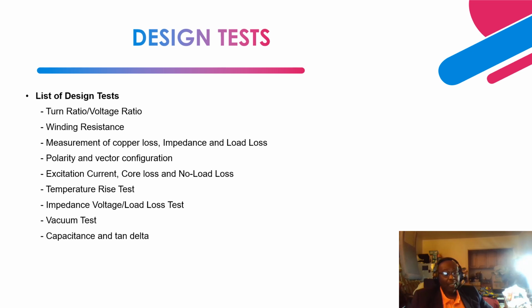And also, during filling of the transformer with oil before energization, that test is done under vacuum to make sure that there is no gassing or bubbles that are going to form. Because those gassing and bubbles, when they form, are going to deteriorate the paper and the oil insulation, and basically compromise the reliability of the oil and the paper when the transformer is in service.